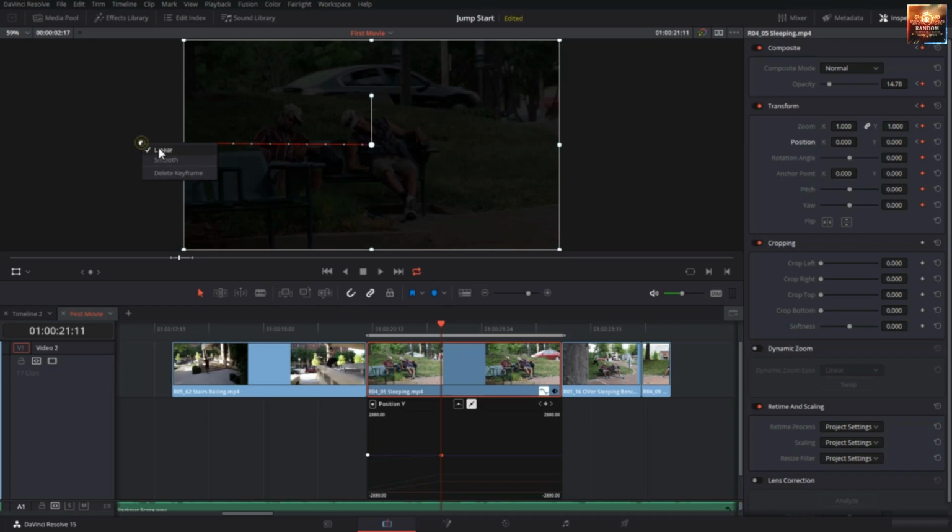And this one also, I think we did it linear. And come back here, right click and say smooth it. I'm not going to move the outer one. I'm going to click on the inner one and just drag it over here. And if you play your animation now, you have a very nice ease in and very beautiful animation.